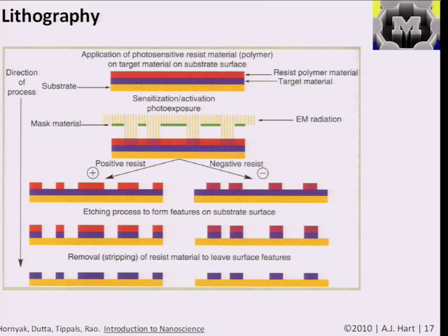But one of the constraints of processes like that is that you don't have control over even the position or the size of individual structures, other than creating a disordered bulk, which also has, in a lot of cases, a lot of impurities or a broad size distribution. So perhaps the most versatile top-down process, which, if it had ultimate resolution, would be highly useful for making nanostructures, is what's called lithography. Lithography, by definition, means pattern transfer, meaning transferring a pattern from one material into another material and copying that pattern over and over to create large areas.